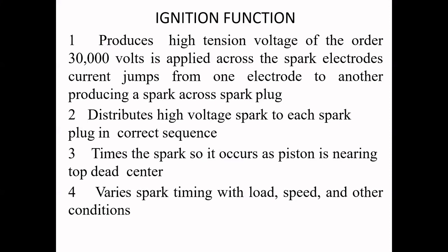The ignition system has to distribute the high voltage spark to each spark plug in the correct sequence. Remember, the battery ignition system, magneto ignition system or electronic ignition system are preferred in multi-cylinder engines.